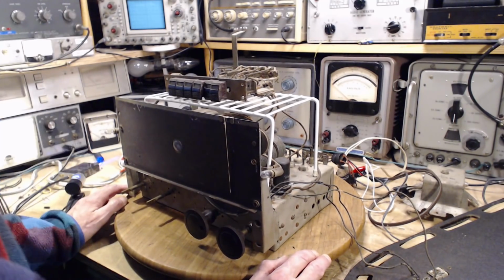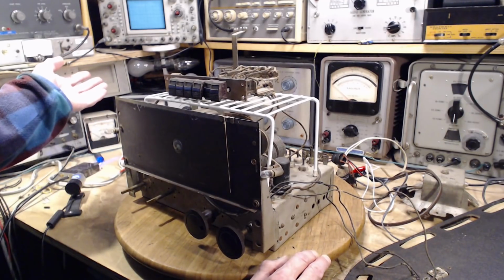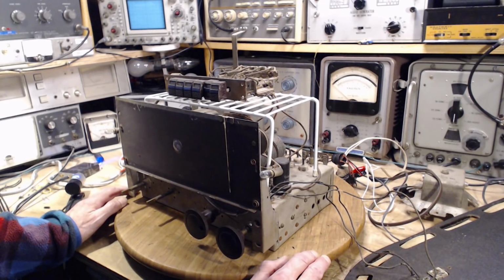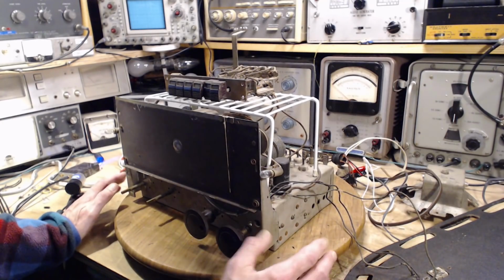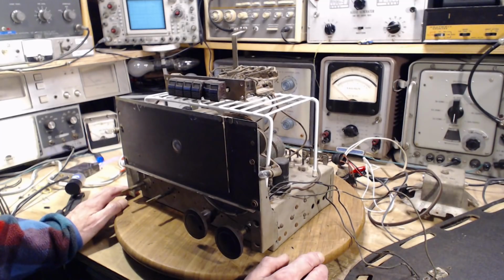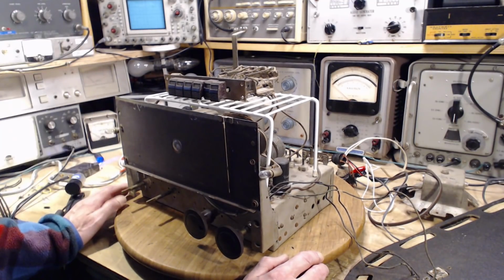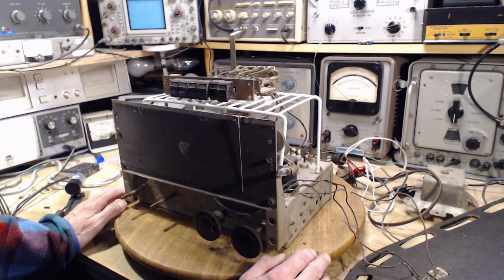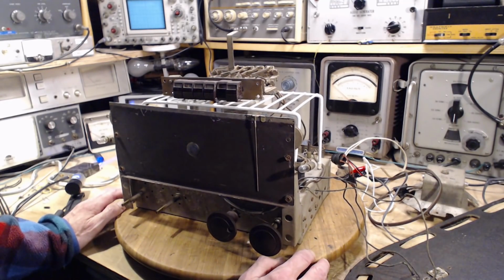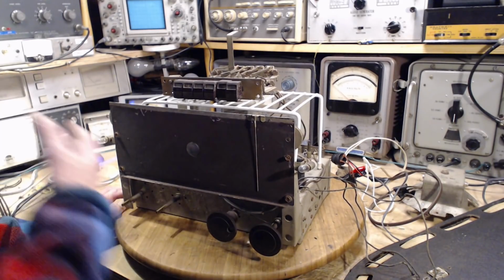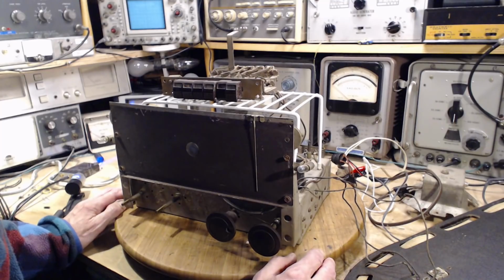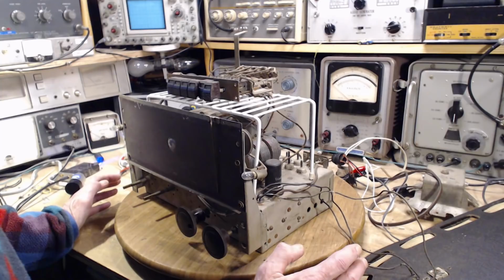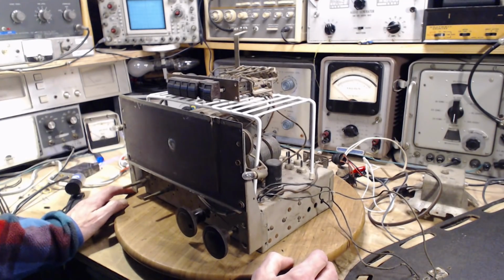So maybe the first thing to do is to set up the oscilloscope to look at what signal is getting to the speaker, and set up the signal generator and get the radio receiving from the signal generator. And then we can start playing around, ultimately changing the capacitors out in the audio circuits. And that's really my intention at this point, is to clean out the old capacitors in here. But I do like doing it in a way that might reveal something more about what has gone on with the radio.